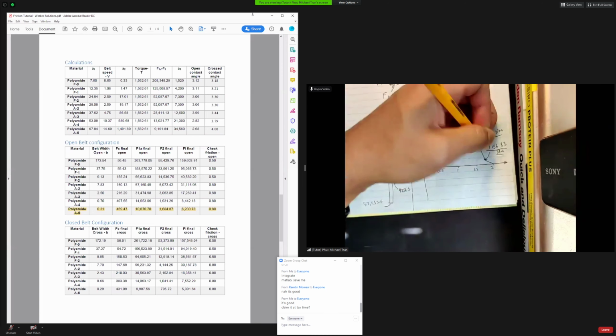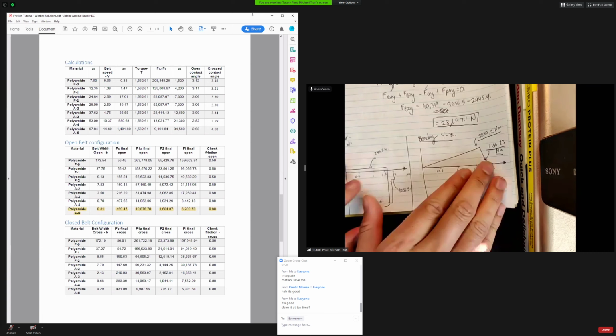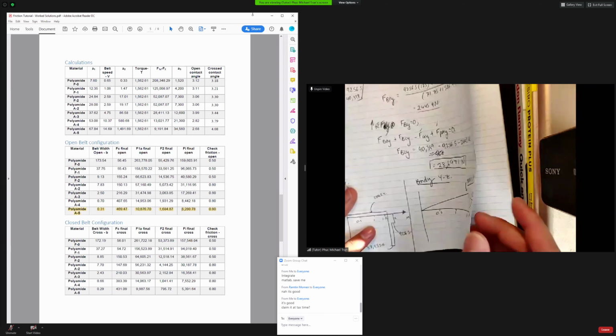Anyways, so you've got the bending moment at 2 points, at the gear and at the bearing. That's where it's going to be the max. So we can find 2 different maximum bending moments if you put them together.